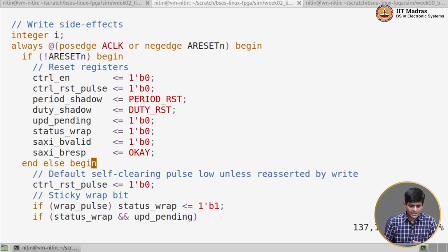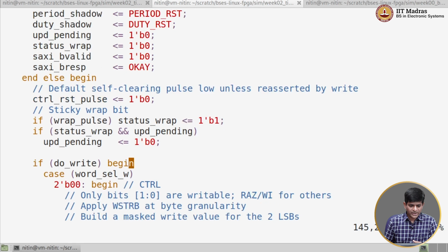Of course, we have a reset condition and a few if conditions, or rather assignments, at the beginning of the always block. Now, you might be wondering, why does it matter whether it is at the beginning or at the end of the always block? Isn't hardware supposed to be concurrent, with everything occurring at the same time? Well, that is because of the way Verilog modeling works.